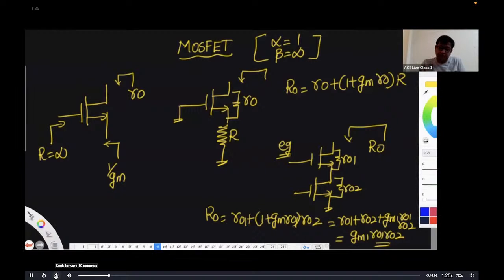So what you can focus on is, if you are given a new oscillator which you have not seen, then you should focus on the loop gain, that's all. What is loop gain? You start at one point, come back to the same point, and multiply all the gains in the loop, and that is going to give you the frequency of oscillation. So if he has given some circuit which you have not seen, then you can do it like that. Okay?